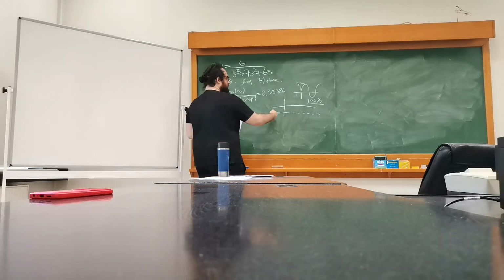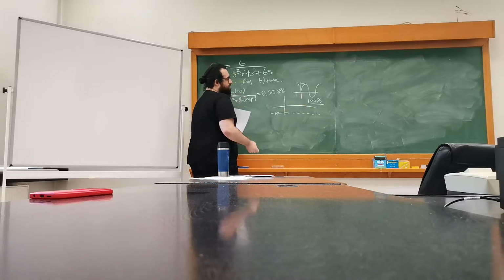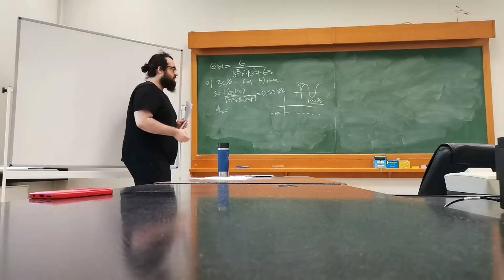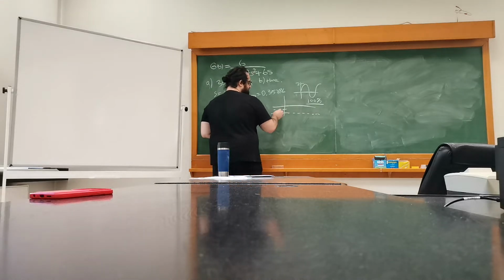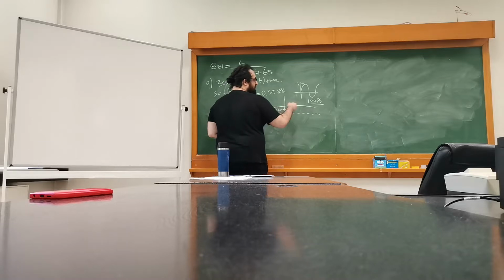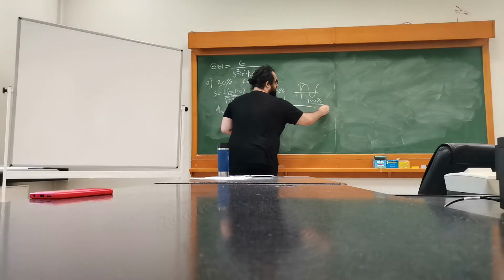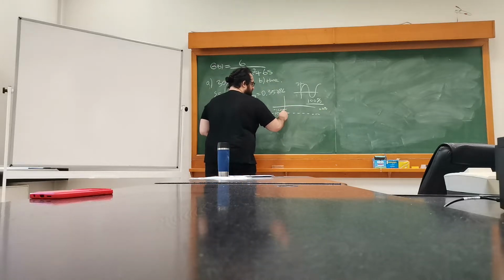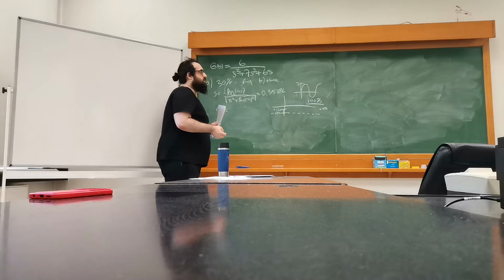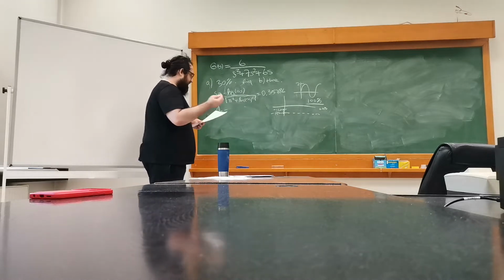So if you have 0 degrees of phase margin, because the difference is 0, then we have 100% overshoot. If we have a certain distance, for 120, we will, for example, have 60% overshoot. So this difference here relates to overshoot in the frequency domain. And for this, we have two ways.